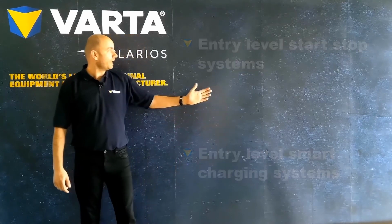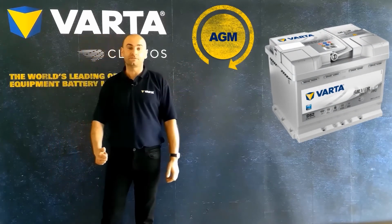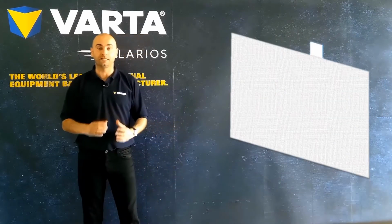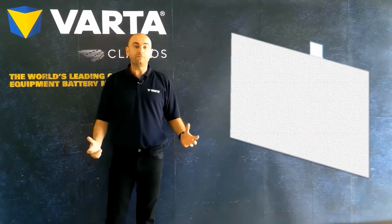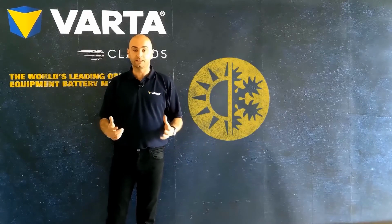And finally, we have the AGM, Absorbent Glass Mat. It's maintenance-free and leak-proof because the electrolyte is bound in an absorbent glass fleece. They're powerful batteries for advanced start-stop systems and have very good cold start characteristics.